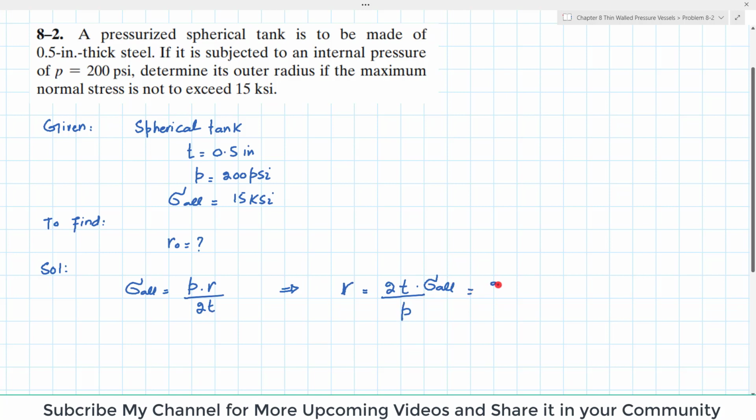Now you have the value, you have 2 multiplied by thickness 0.5 inch, clear, and allowable stress is 15 ksi, so 15 into 10 to the power 3, clear, divided by pressure 200 psi. So when you calculate it, you will get R, which is the internal radius, equal to 75 inch.